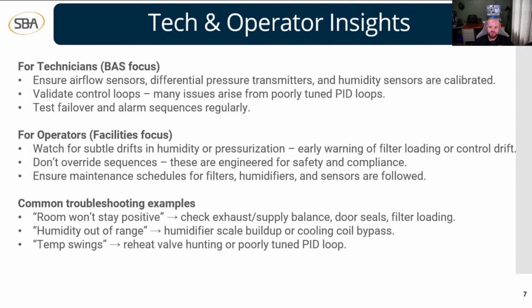Big thing here is just always check your filters, guys. Filters are going to be huge. Remember, HVAC is big on airflow, and if our filters are clogged up, if they're filthy, we're not going to get very good airflow through our air handler, and that's going to cause our rooms to go way out of whack. So make sure you're checking all these things when you're doing your troubleshooting. It'll help you out a bunch.